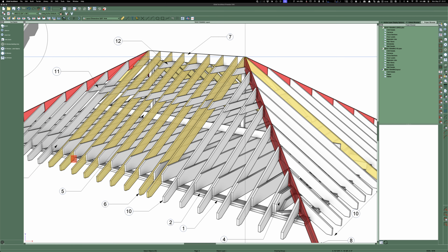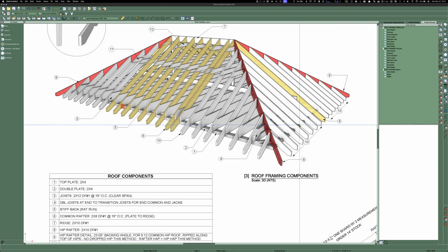And this way is better. It doesn't take much extra time either if you just do it. When you get to the ends, you double a joist, and then you turn direction. You put 2x6, 2x8, whatever out. So you create a completely sheetrockable ceiling.